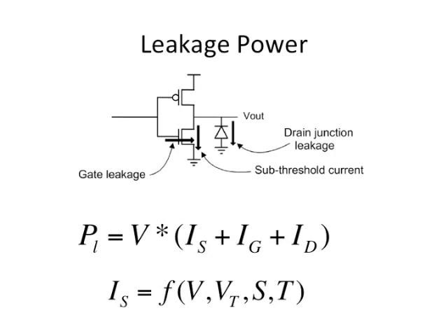Good questions, actually. So the leakage power is the power when I'm not transitioning, but I still draw power, because my transistors are not fully off, right? So let us say here my input is low. Then my PMOS is on, but the NMOS is supposed to be off. But I have a subthreshold leakage current, because across the NMOS I have a VDS which is not 0, right? So I will have a subthreshold leakage current which is given by IS.